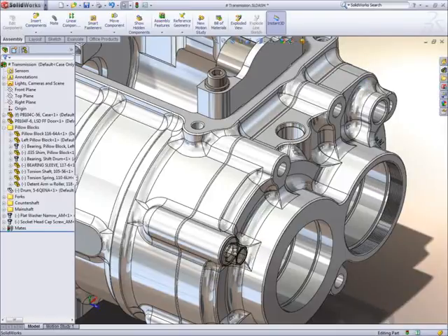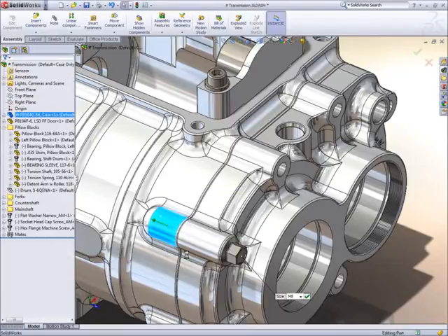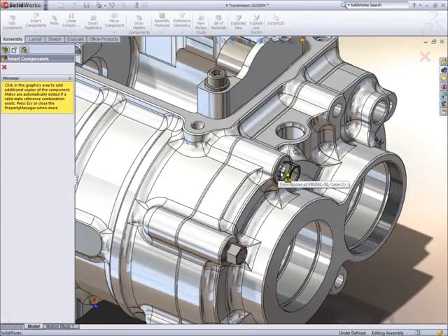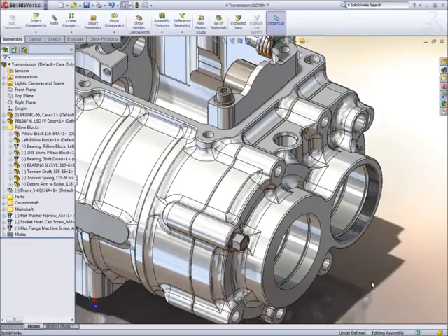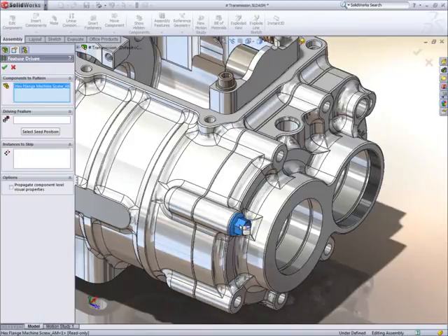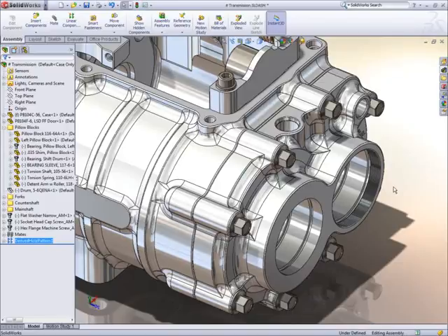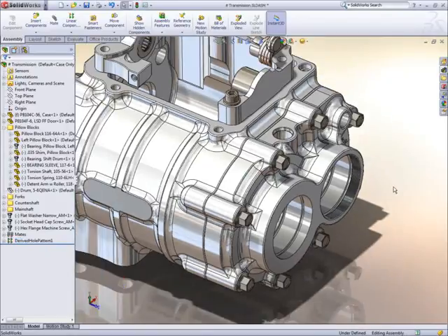Selecting the correct size fastener is fast, but you don't need to add the mates manually, so you're saving yourself a lot of work. Though some designs may call for a lot of fasteners, and you certainly don't want to add each one individually. So the last used fastener can be placed as many times as you like, using Smart Mates to speed up the process. If the fastener is added to a hole that is part of a pattern, the rest of the holes can be automatically populated. This again is fast, but also, if the number of holes should change, the number of fasteners will change as well, so your assembly is always up to date.